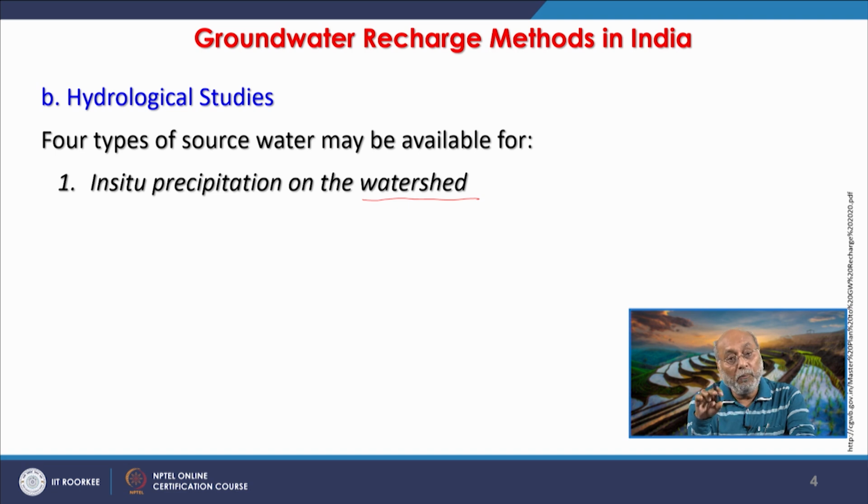If we follow political boundaries, then our estimates may go wild, because the rain does not know political boundaries, but watershed boundaries, coming through the topography or ridges and other things, have control over this.